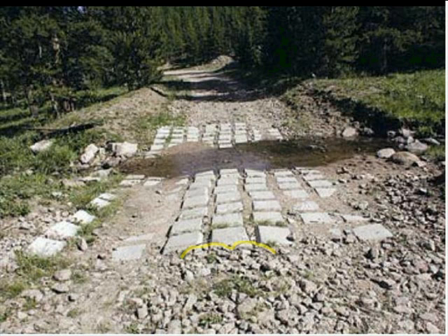Here's a shot of a cable concrete crossing on a relatively steep transport reach in Wyoming where the mat wasn't extended up the bank line as high as necessary. In addition, the subgrade at this crossing wasn't well compacted because of the presence of large boulders. Erosion and settling at the site has exposed some of the structural cables, which can be a hazard to passing vehicles. It's rough to drive across, but functional from a passage perspective. However, sites like this where the blocks have begun to move around often fail over time.